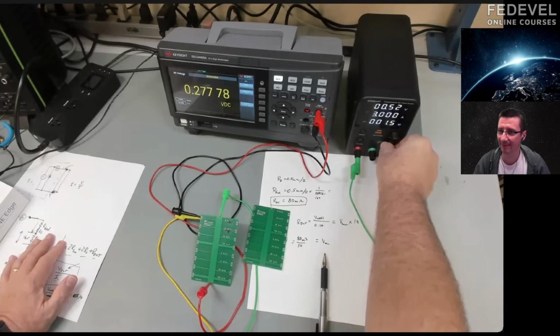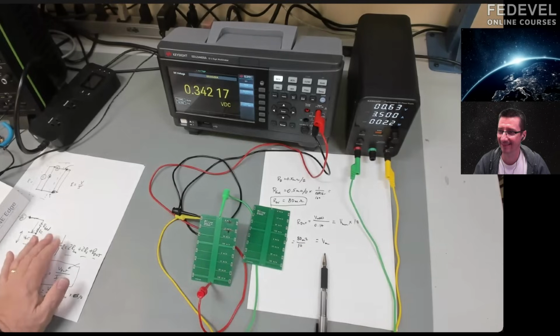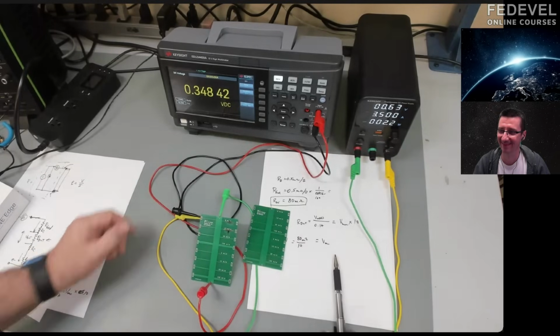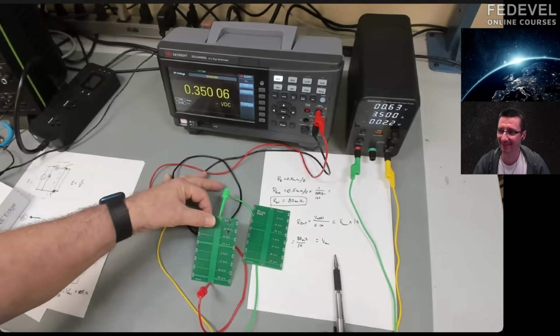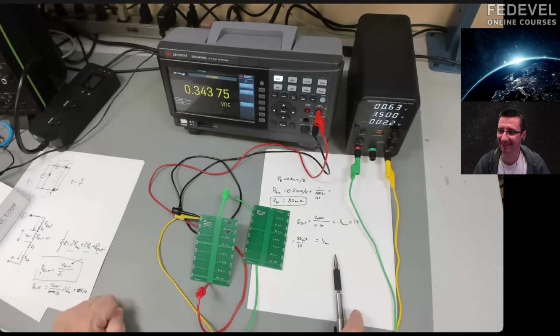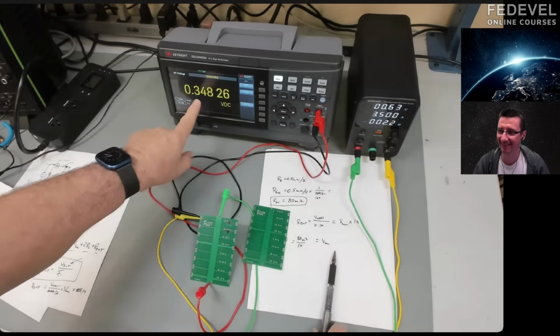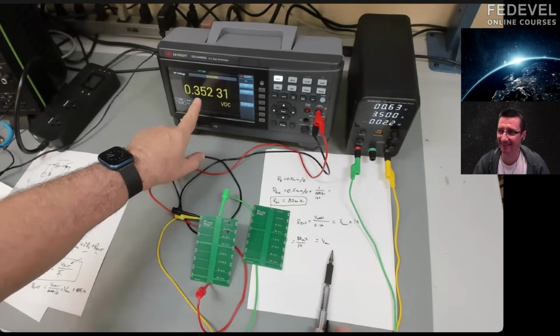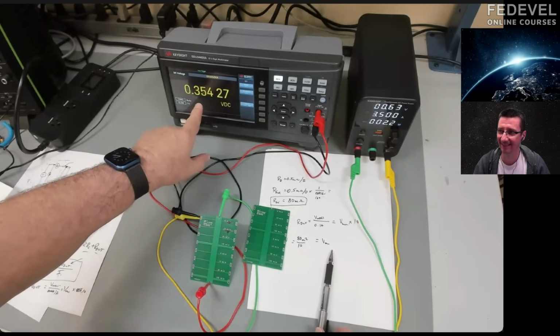I'm going to get that digit. And so now we're up to 3.5 amps. Think about 3.5 amps through that tiny little 6 mil wide line. And the resistance is increasing. If I touch it, ow, that's hot. I'm not going to touch it much more. We watch that voltage slowly increasing at 3.5 amps. It'll probably reach equilibrium here.